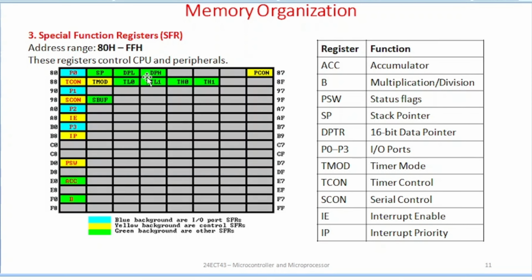The program status word is used to check the current status of arithmetic and logical operations in different bits. The 8051 has 4 mathematical flags that respond automatically to the outcome of arithmetic and logical operations, and three general purpose user flags. The math flags are carry, auxiliary carry, overflow, and parity, plus one user flag, and two bits are for the selection of the register bank, RS0 and RS1.